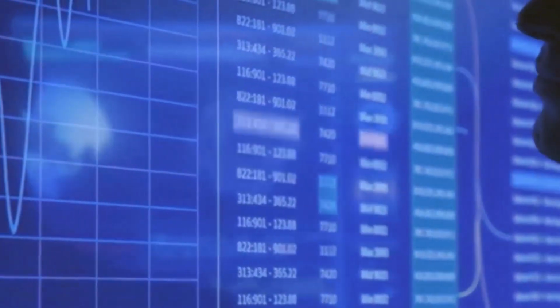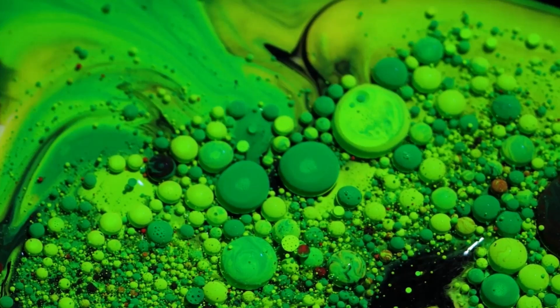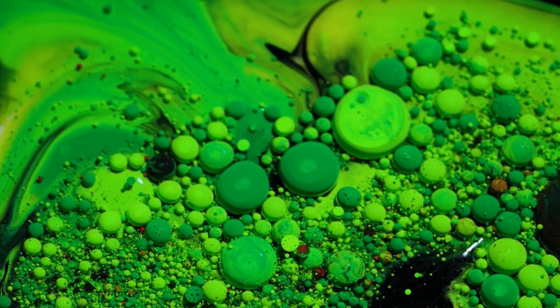The flow is laminar, meaning it's orderly and predictable. This is the place where the transfer of forces and heat from the fluid to the object begins. To accurately predict things like friction and heat transfer, we absolutely must understand what's happening in this viscous sublayer. And the only way to do that with high fidelity in a simulation is to place our measurement points directly inside it. This is precisely what aiming for a Y+ value of about 1 accomplishes.